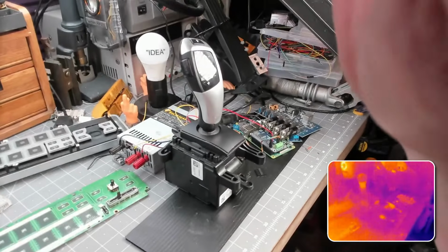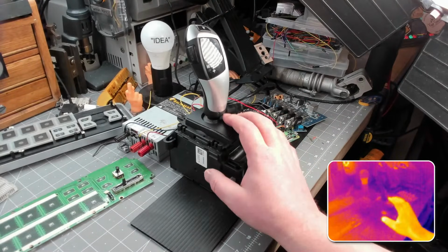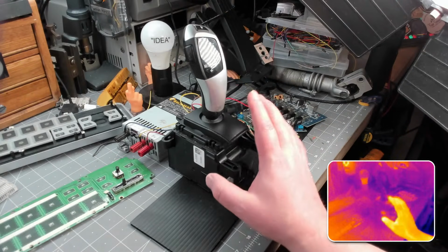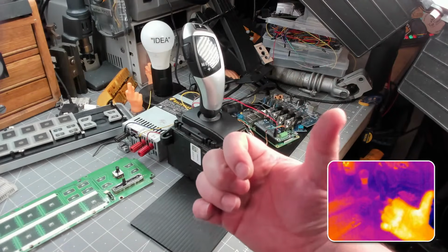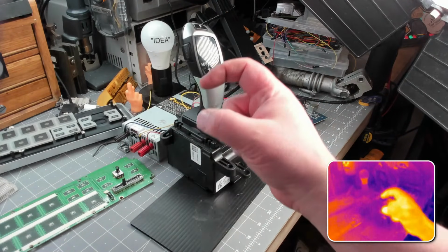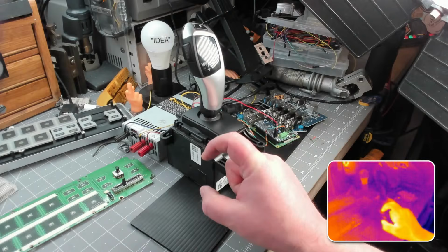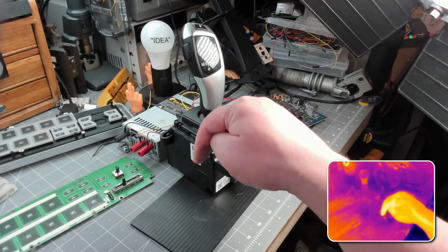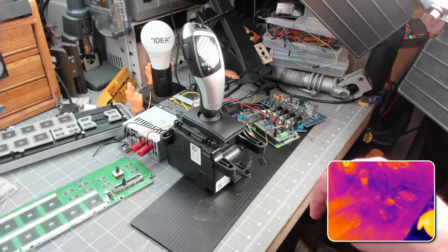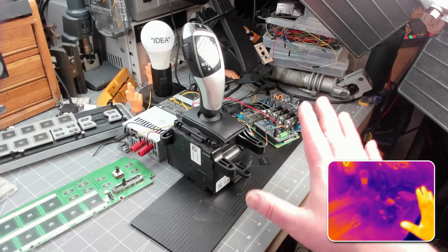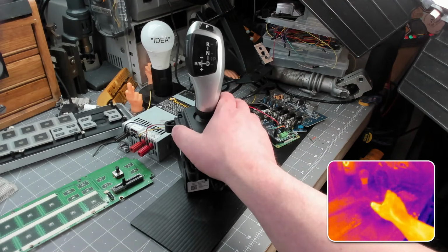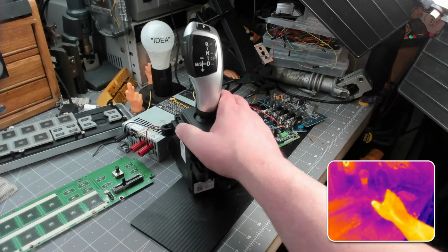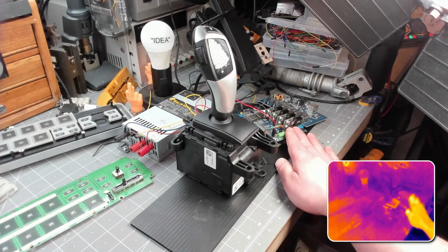We'll get there. We worked with the shifter a little bit. The shifter works on possibly the faster CAN bus, so we were able to get the faster CAN bus communicating with this. If the seat speaks a different CAN bus, I will have to put a microcontroller in there as a moderator so that it can receive the 500 kilobit CAN bus and relay it to the 100 kilobit CAN bus. I don't want to have to do that, but if I do, I will. So we got this thing communicating, and that means that our faster CAN bus is speaking to the Raspberry Pi.